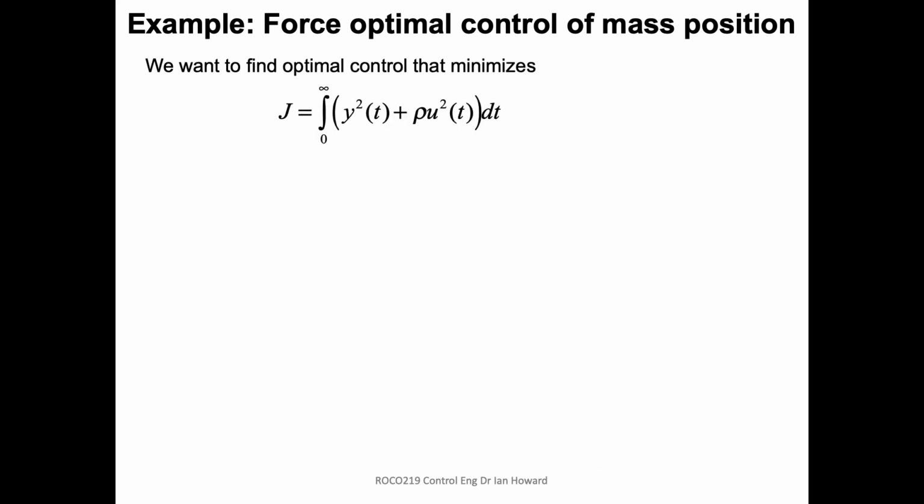So we're going to use a controller which basically operates by minimizing the distance, which is going to be y squared, and some scaled version of the control, so rho times u squared. In this particular case, obviously we're talking about 1-by-1 values for y and for u, so we don't have to write these in matrix form. They can be put in directly as scalars. We're going to formulate this as the optimal control, linear quadratic regulator problem.